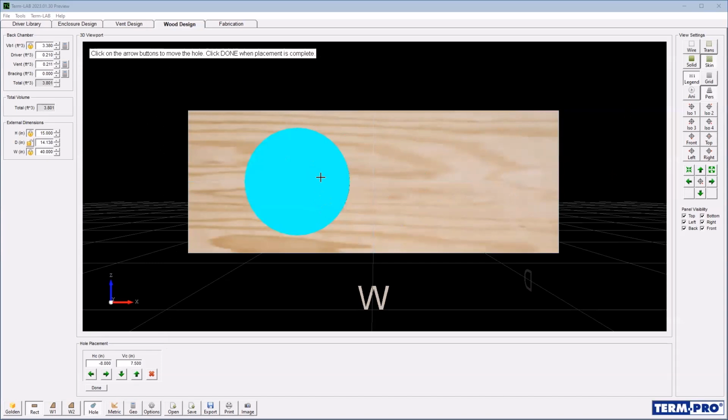So keeping the subs close together in the center of the box is going to provide better results than if you put them towards the outside, because in a system with 4 subs, the loading would be different, and you might encounter some phase issues at high sound pressure levels and low frequencies, where you can see the cones actually slowly being out of phase with one another. Anyway, in this design, we're going to keep this sub at this location.